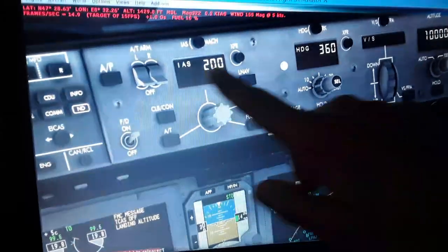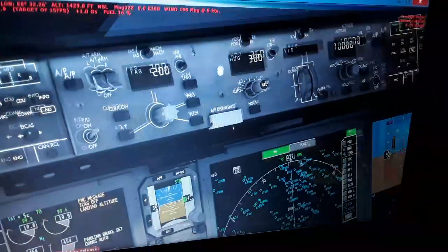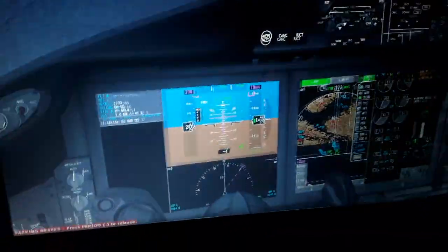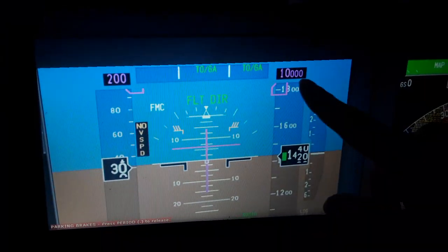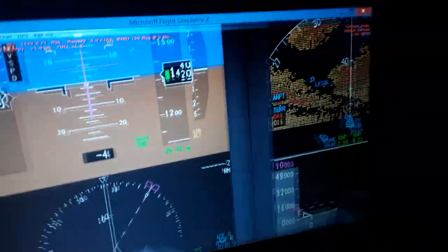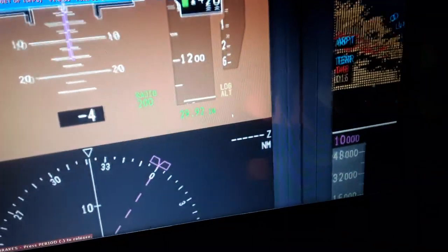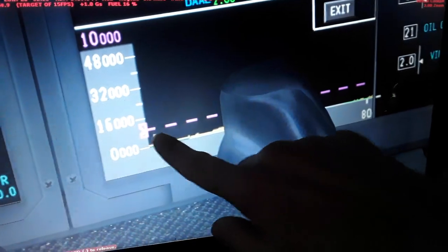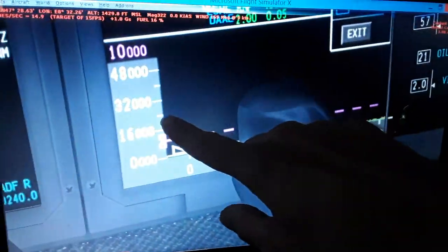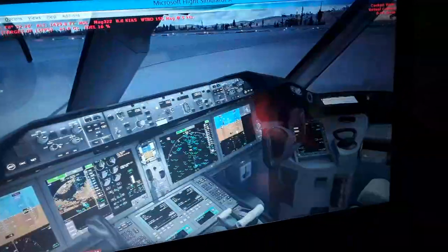Autopilot flight director system panel. Later you see same airspeed, heading and altitude, like the values selected and displayed here in the primary flight display, both sides. You can see airspeed and altitude selected, and also heading over here selected 360 degrees or 0. Also the altitude we have selected 10,000 feet. It's also displayed in the vertical profile. We're going to be flying. You will see we're going to select a higher altitude for flying. You will see the aircraft flying above the terrain in front of it.